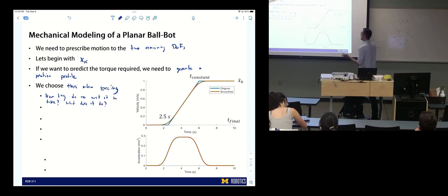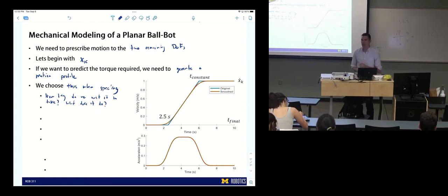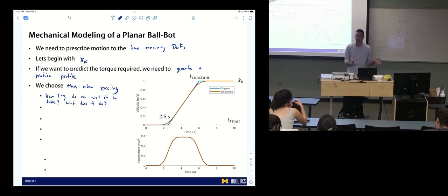And then the question would be, how long do we want it to take to get up to 1 meter per second? I chose 3.5 seconds, which doesn't seem too fast, seems like a reasonable time for it to get up to that. Obviously if we make it take longer, that's a lower acceleration, easier for the motor and actuator to do. If we try to make it faster, it's more acceleration, which is harder and produces more torque, more current. So we want to spec these based on what we want it to actually do. I think 1 meter per second seems about right.